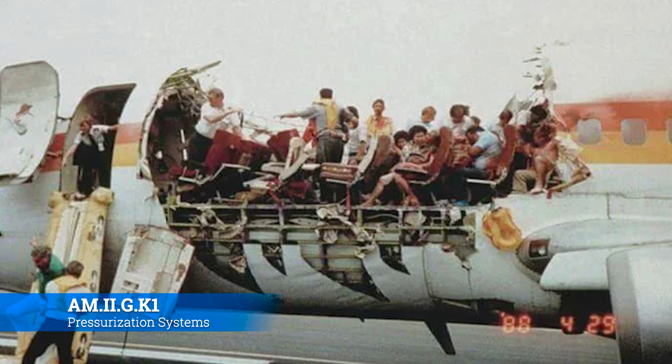Okay, so this is Aloha Air 243. Now, I believe we've talked about this before, but effectively what happened is that you see right beside the crew door there, just going aft on the plane, that's where the separation of the fuselage happened. There was actually a row of rivets that gave way. Now, corrosion was a major factor in all this. The corrosion inside of those rivets had eventually weakened it and weakened it and weakened it. But what happened was whenever the aircraft got to a certain altitude, the differential cabin pressure blew that front part of the fuselage up.